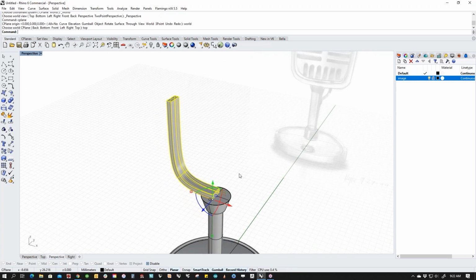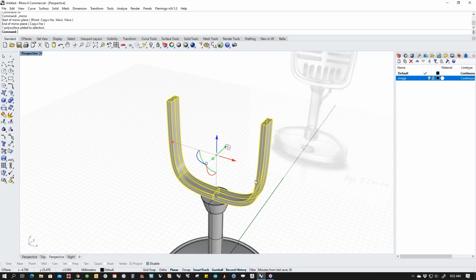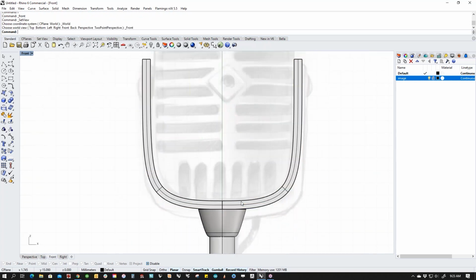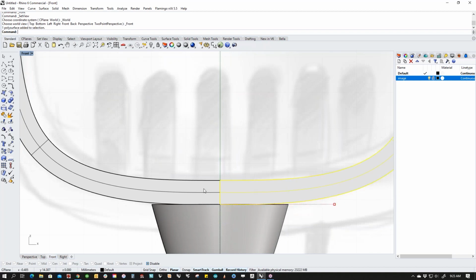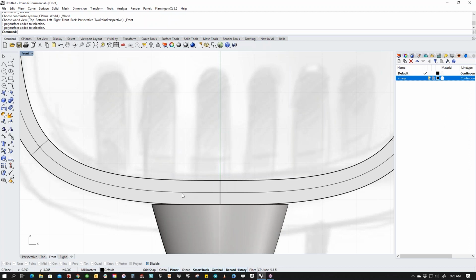All right, so we've got this piece built. Let's go ahead and mirror it. And I just use the mirror command there. And you can see that in this case, we can evaluate this and see how we did as far as centerline tangency. And in this case, it looks pretty good. But we can also double check that if we look at our original curve.